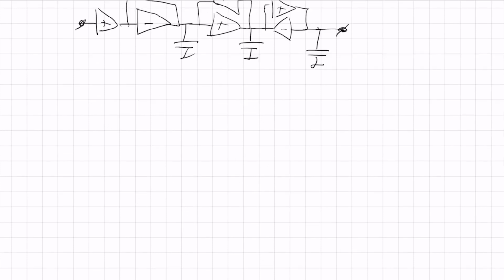Well, you may think, how can you make a transconductor? A very simple one is a CMOS inverter with a PMOS and an NMOS transistor. If you bias that one in the middle, so not like an inverter, but somewhere in the middle, then if you increase the voltage over here, this one starts to sink a current, and this one starts to sink a current as well, so you pull a current in. So this has a negative GM.